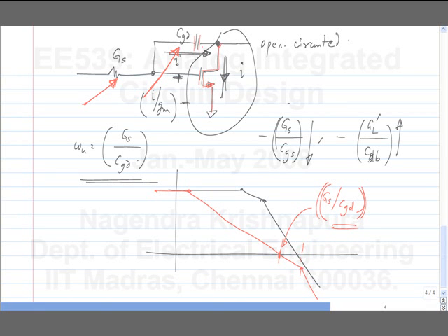And in particular, the response we want is that of a first order type of system which helps us make feedback amplifiers. If we do that, then we can manipulate the value of CGD to get the desired unity gain frequency. Okay. And also perhaps to stabilize it. We know that if we start with this black response and put it in a feedback loop, it will be unstable or it will ring a lot. So, we will try to manipulate it so that it becomes something like this. Okay.